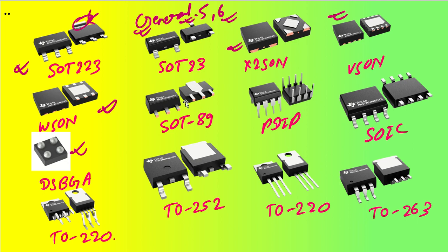One very good advantage of the linear regulator in the SOT89 package is that with almost the same area, it has greater capability of heat dissipation. So this has very good thermal power dissipation. If you need good handling capabilities, and you don't want to handle SMD packages, then you can go ahead with a through-hole package like the PDIP package. The regulators are also coming in SOIC and TSSOP packages, HTSSOP packages, all those things. Even VSSOP packages are also available.